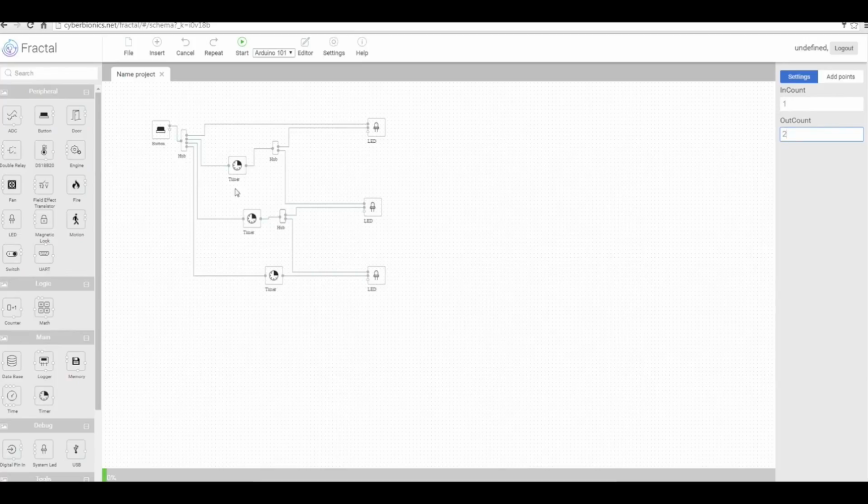As every timer, according to the previous logic, counted down 3 seconds, so now for simultaneous activation, we will change the time after which the timers will give commands to the LEDs with 3 seconds difference for each. So we set 6 seconds for the second timer and 9 seconds for the third. And now the circuit is ready. As you can see, the logic of construction can be different. Fractal gives an opportunity to choose the most appropriate way for each person.